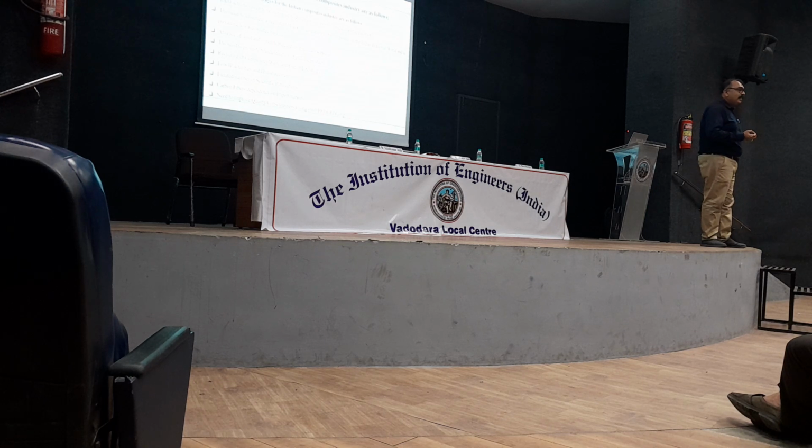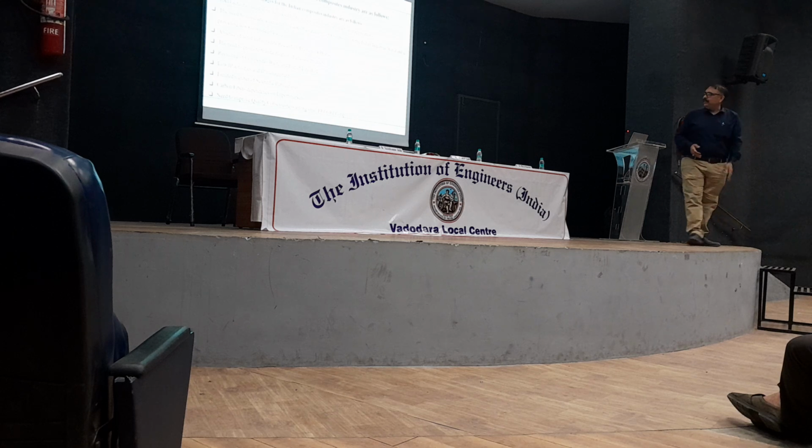So what kind of delaminations are there? While we are drilling, what kind of thrust force is developed, etc. These are various interesting research studies that are developing. So it is very important that we work on each criterion, even this small topic, machining. People will say it is only a drill, what is happening? But once we see under the microscope what kind of cracks are developed, what the delamination at entry and at exit is, what the surface roughness is, because these are the parameters which create or accelerate catastrophic failures.